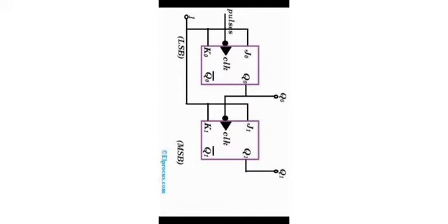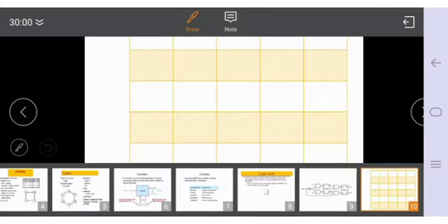This is our 2-bit JK flip-flop counter. Initially, if we take Q0 as 0, then the falling pulse goes to Q1. So Q1 changes to the complement of Q0, which is a high value. And if Q0 is equal to 1, then Q1 gets 0, and this process continues similarly. So we can plot the frequency division of the clock.